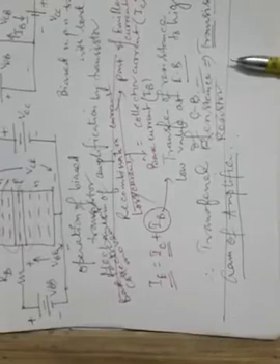When an AC voltage is superimposed on the DC voltage VEE, suppose at the input, VEE that is being applied at the input, a voltage source, in that case there will be a periodic variation of emitter current, which in turn will give rise to a similar periodic variation of collector current, because once the alternating signal for amplification purpose is applied at the input of the BJT, that will make the input signal vary, which will eventually result in the output signal, that is the collector current, also being varied.